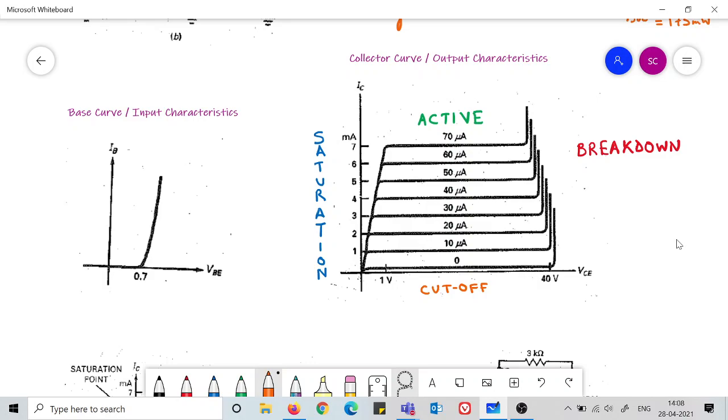When we were reading about diodes, it was very interesting, something new. But now it is very standard to us. It is not interesting. What is interesting now is this new characteristic that we see when we plot VCE versus IC. Now remember, what does the output characteristic mean? We have to deal with the output current, and IC is the output current because it is what is coming out of the transistor and going into a subsequent circuit where we have placed RC.